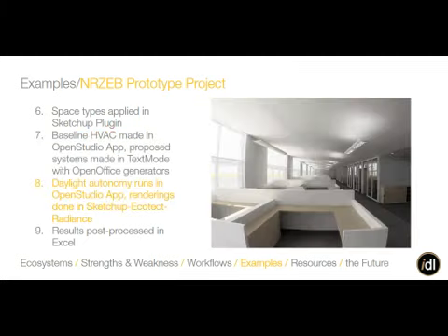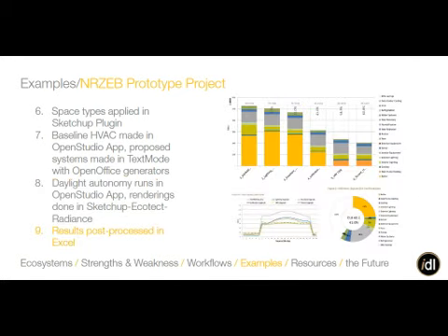It's the first time we ever took it that far, where we used OpenStudio for the baseline HVAC modeling. Then we did daylight autonomy runs in OpenStudio, but we still had to do the renderings in SketchUp to Ecotect to Radiance parallel workflow, which I'm embarrassed to say, but it just wasn't quite there when we did the project, so we could do it all together. And you really can't get good perspective visualizations out of OpenStudio yet, but I think they will integrate that further down the road.